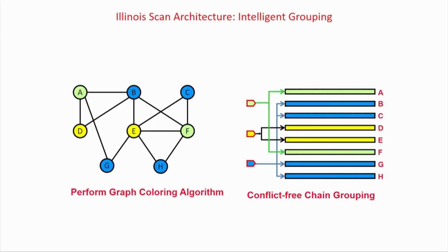But anyway, first we have seen scan, then you have seen partial scan, then you have seen how scans can be parallelized, and then you have also seen how it can be optimized in terms of number of input pins, as well as you should not have too many input and output pins for your scan. Still you should have parallelism, at the same time you should not make test faults untestable. So taking everything, it is an optimization problem which can be solved in this manner as a graph coloring problem. So this mapping I have showed you. So this is one way of optimizing the scan, and as I told you, if I talk about DFT, scan actually plays the role of more than 99% of area, or you can say algorithms, or your space complexity, or the main heart of DFT is scan chains.